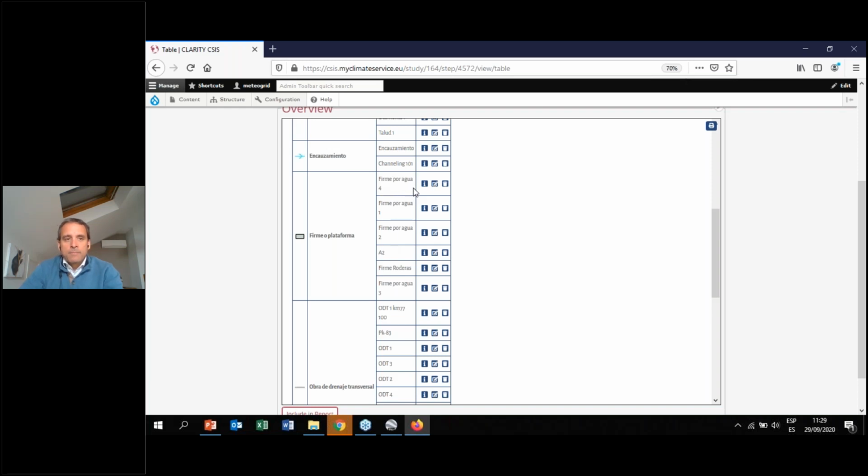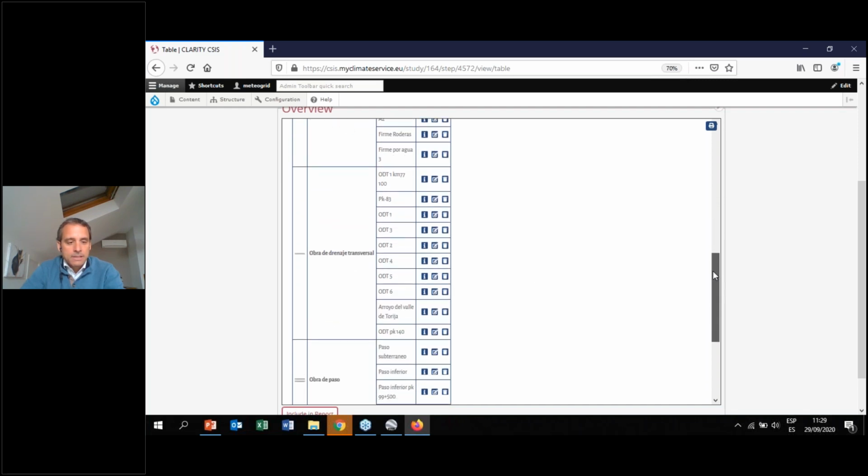For example, not enough drainage capacity, or problems by intense rain or heavy rain, or identify, for example, physical problems of the pavements, where deformations due to heat waves or deformation to the elastic behavior of the pavement. So different, again, transversal drainage, identifying different points along the road.